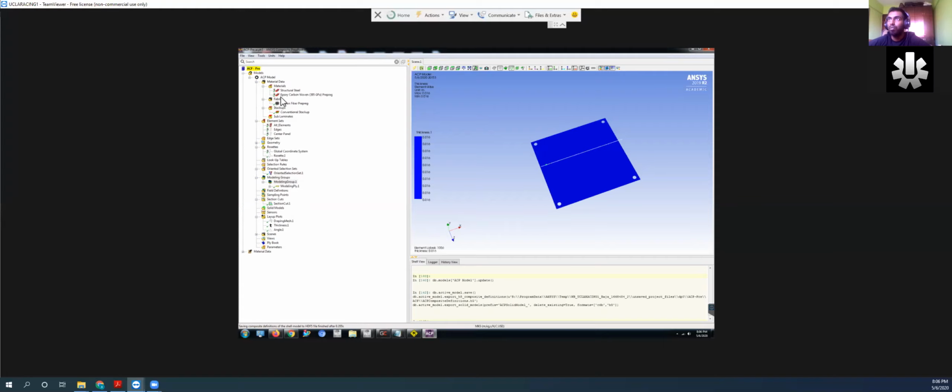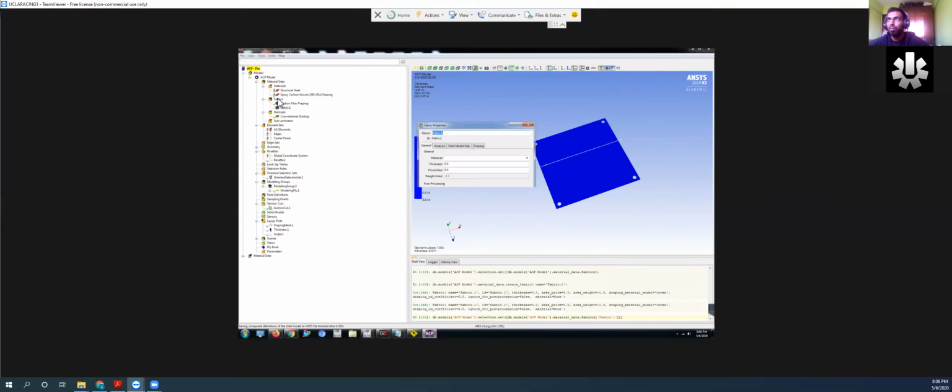All right, so first thing that we want to do is, under material data, there's two options called materials. So open up, it'll all come collapsed. You want to open it up, make sure that you have epoxy carbon woven there. This is really important for later checking. And once you check that you have the appropriate material there, click on fabrics, and usually you should come up with a right-click option, like create fabric.